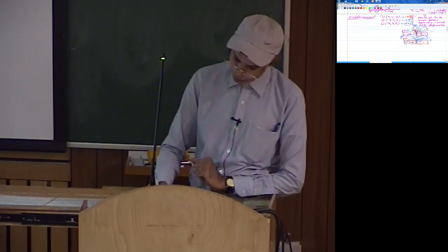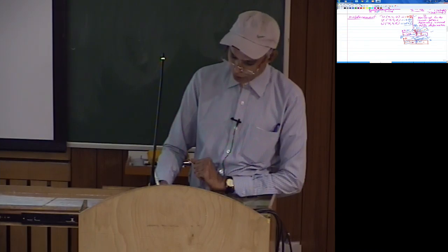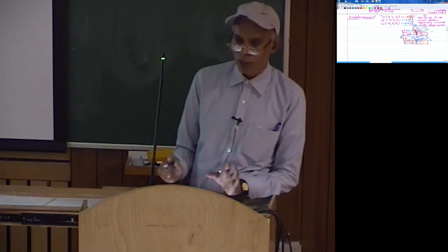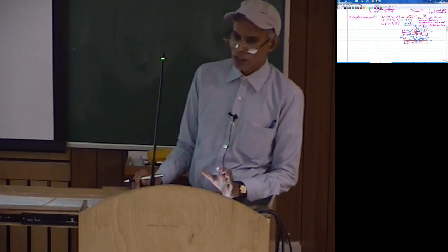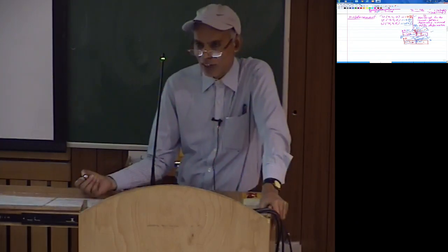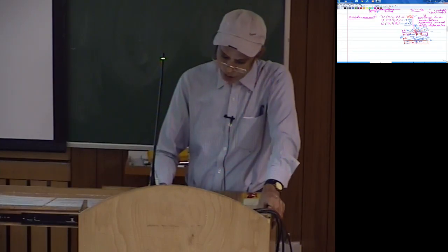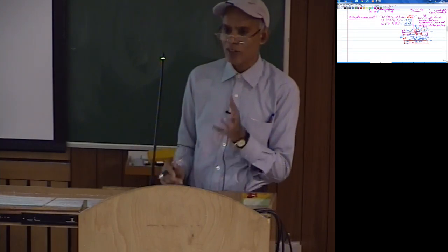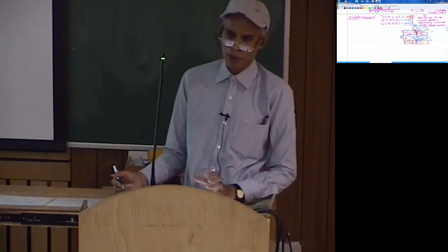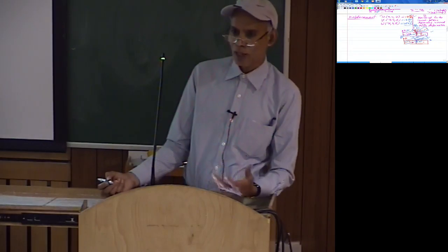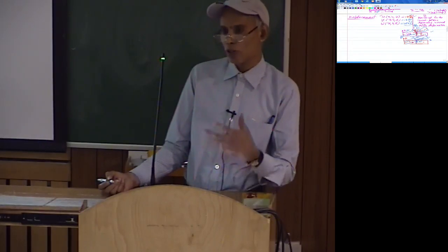The main assumption here is that the normal to the middle surface remains normal after deformation. So then we have only one unknown variable, w, which is a function of x and y. Now if we relax this, if a by h, let's say, is less than 30, then the normal may not remain normal, but the angle between the tangent to the deformed middle surface and the normal drawn in the undeformed surface will be at some non-90 degree angle. So there is a transverse shear deformation. Then you have to consider these rotations independent of del w by del x and del w by del y, so you introduce two more unknowns.